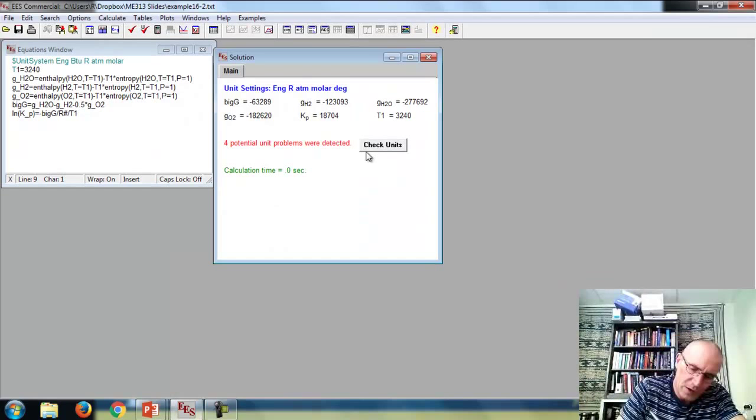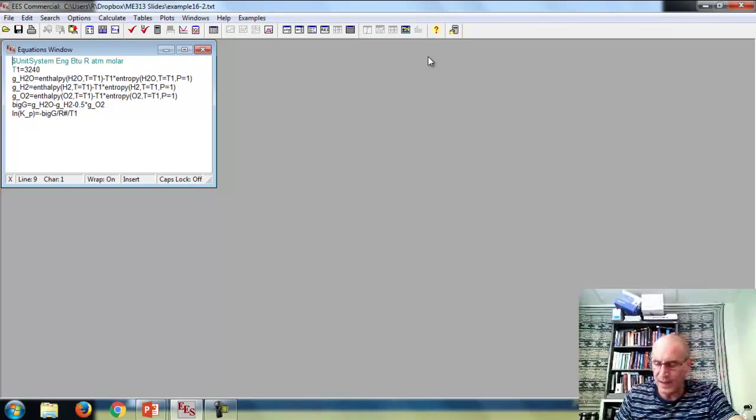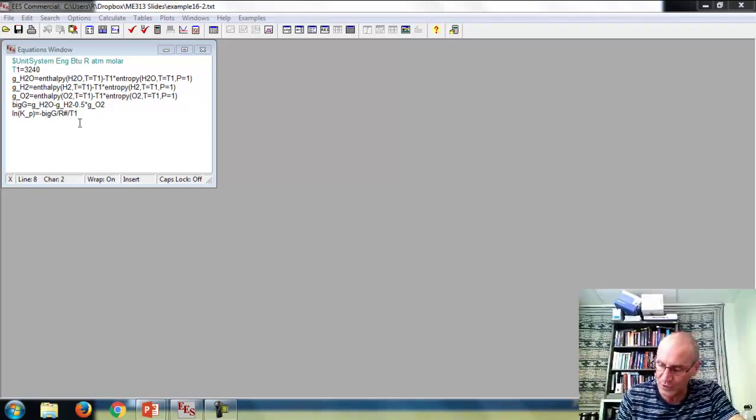Okay, so here I've got the problem in EES. And so let's go up here. Let's look at first an important thing. I'm setting my unit system to English. I'm setting it to BTUs, temperature in degrees Rankine. I'm doing my pressure in atmospheres. And I'm also setting it equal to molar units. Okay, so here I've defined my temperature T1 at 3240. That's the temperature I'm trying to use.